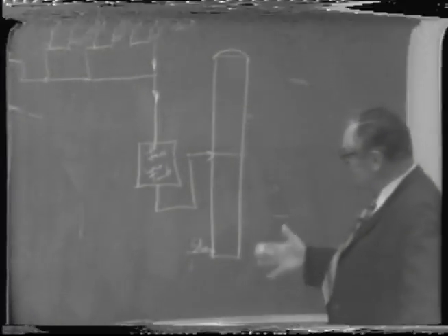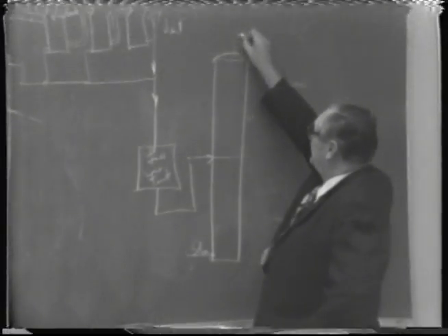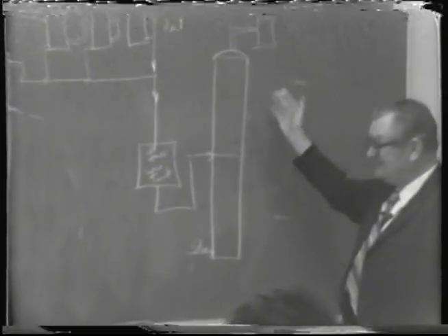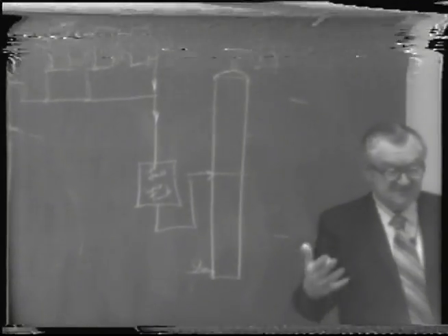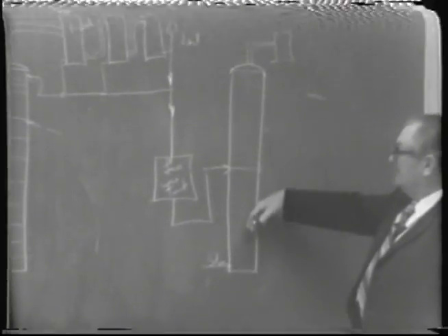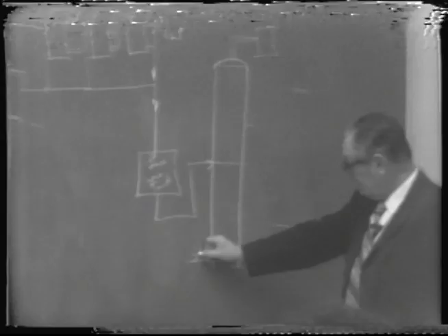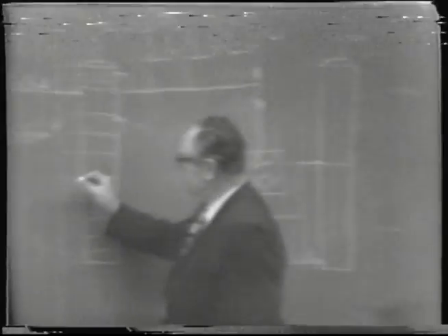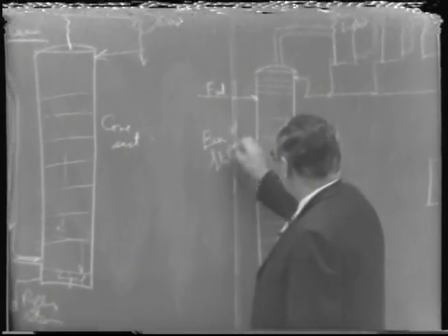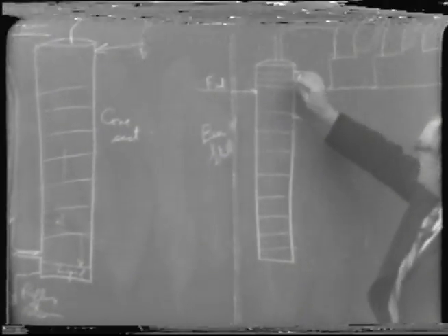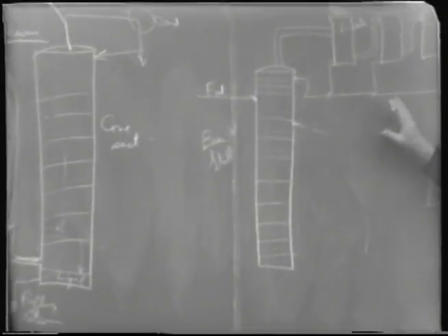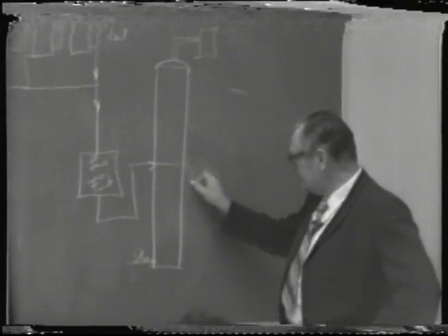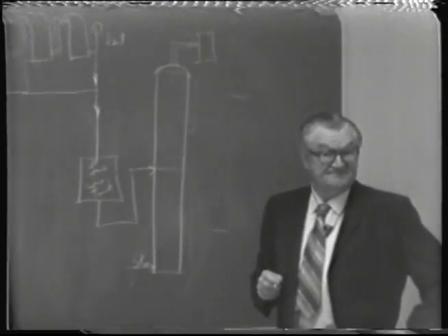And of course, this could constitute the rest of a process to make, let's say, relatively high-proof spirits. Not the cleanest high-proof spirits, but you could use a system like this, where now you've got a beer still over here, which essentially consists of a stripping section, maybe a very short concentrating section. But now you introduce this into another column, and so now you have a stripping section here and a concentrating section here. What's the advantage of that?